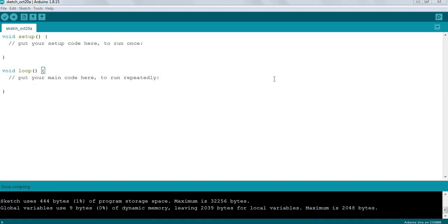We know that LED is an output device and hence the pin 5's mode should be set as output. So now this pin is ready to provide output to the LED. First we want to switch on the LED. And we know switching on and off means there are only two values, which means we are talking about digital values. And hence we will use the command digitalWrite.